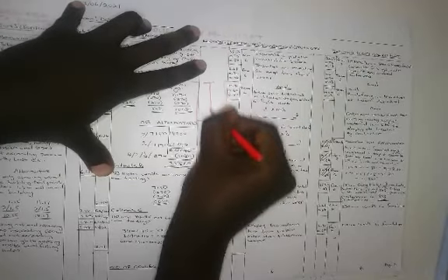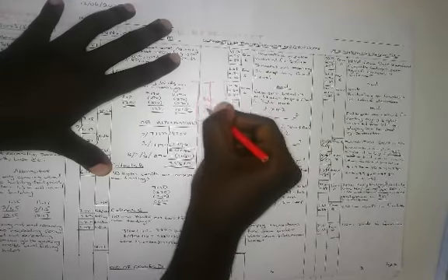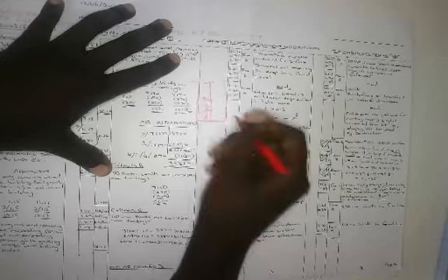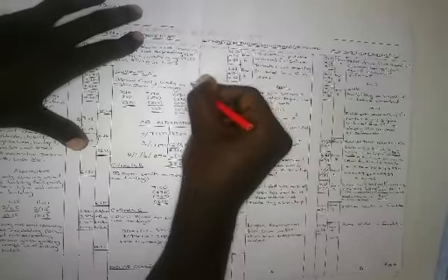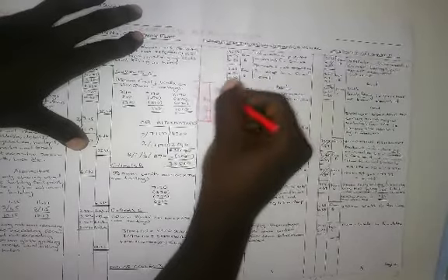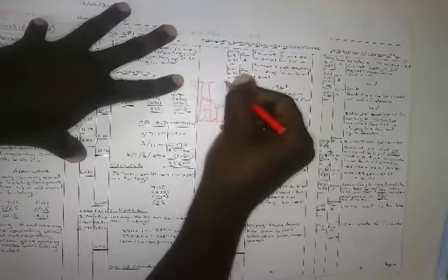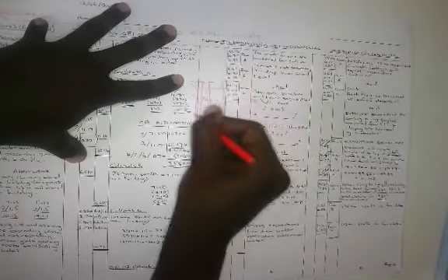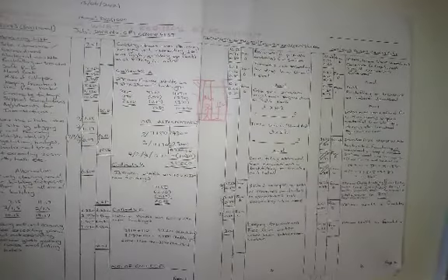Let's say, for instance, let me draw a trench for you. Let's say this is a trench. Let's say from here to here is 3 meters, okay? And the person is here, working here, say 1.7 meters. If this soil over here collapses into the trench, this person is going to die, okay? So hence we need to protect the trench and put some supports on the side to keep the trench together. That's what we talk about when you talk about risk of collapse. It means protect the trench.